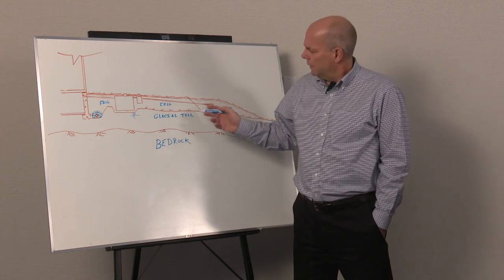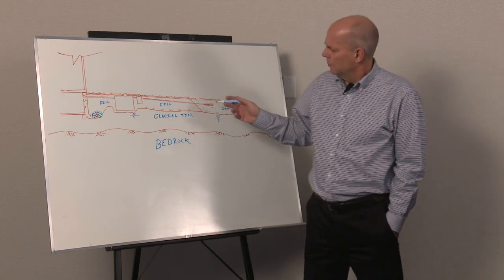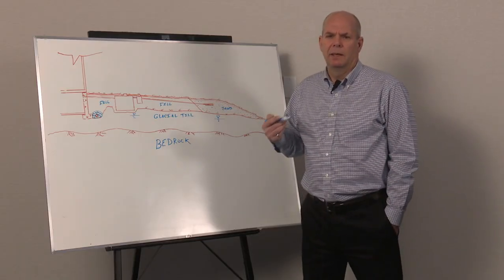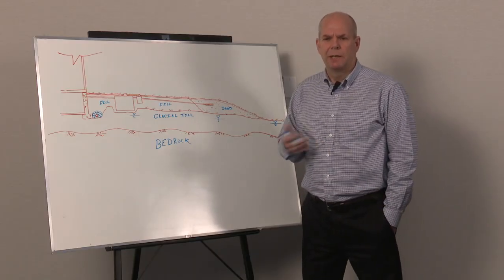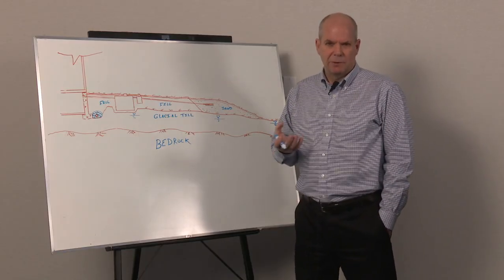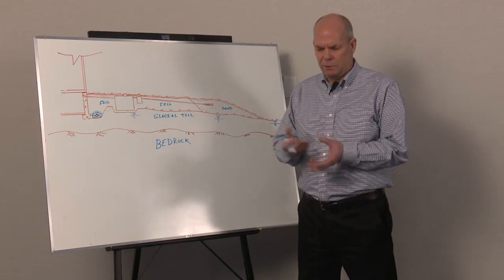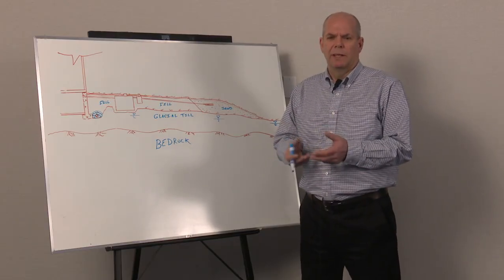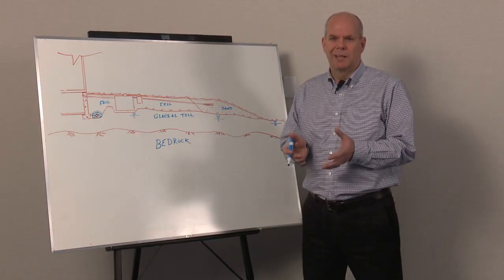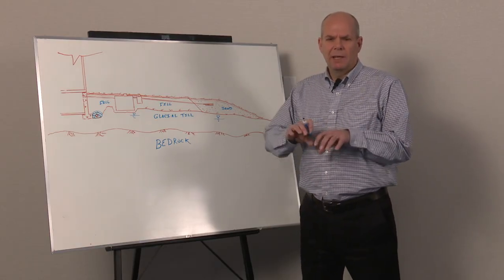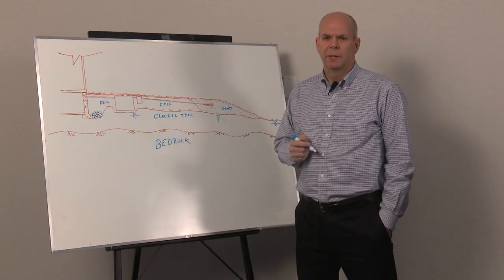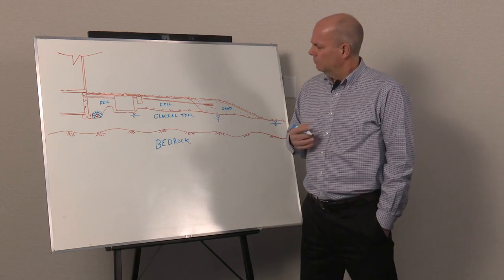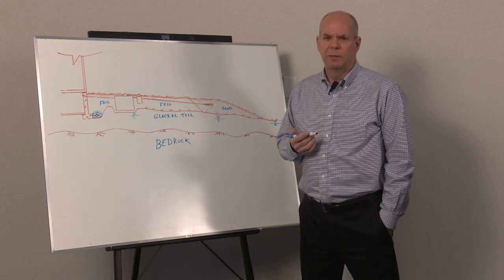The glacial tills, as I talked about before, are basically sand and clay based. So the sand will vary from a silty sand to sandy silt, but its behavior is more typical of a sand, and a sand will kind of fall apart and break down into a little pile of dirt, basically. Whereas a clay is plastic, deformable, you can shape it, mold it. It has completely different behaviors and will give you much more difficulty if it's not handled properly.